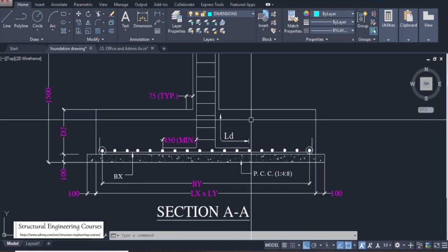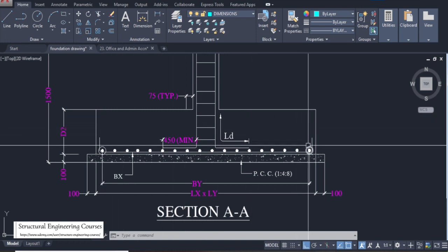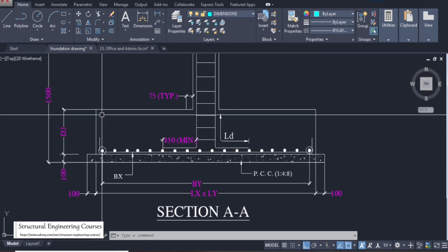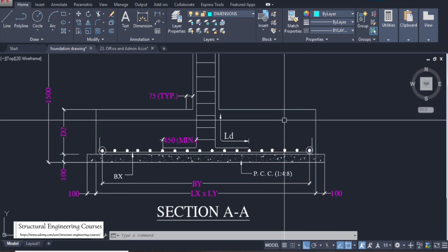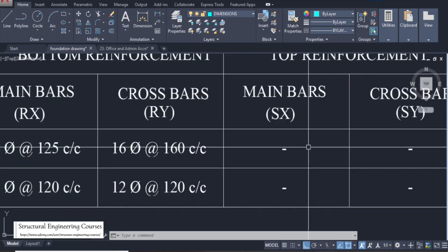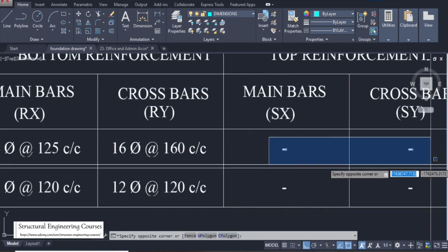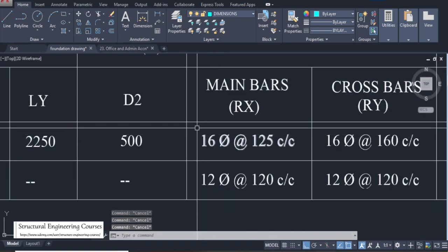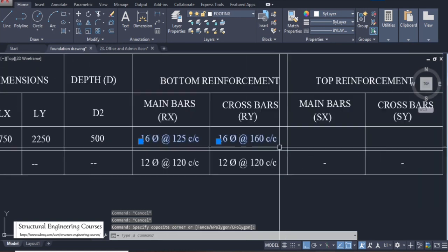Because we don't really need reinforcement bars on the top face. If you are typical or conservative about all this, then you can provide a nominal number of bars on the top. Let us say we can provide 10 dia 250 mm bars on the top.